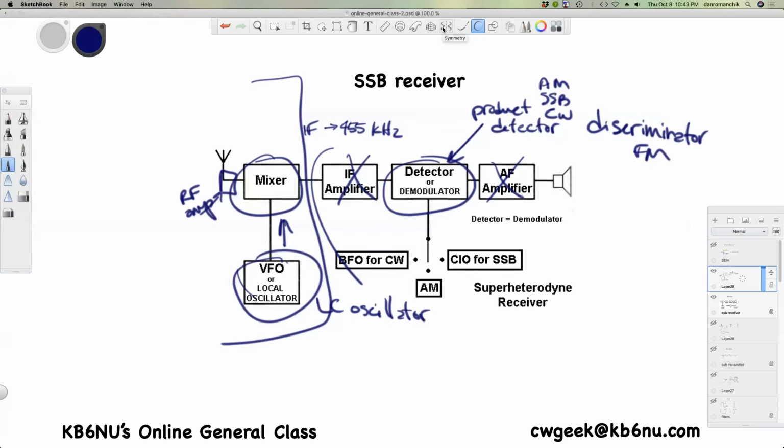That's why you sometimes had to warm up your radio before you would use it, because you wanted the most frequency stability. After the temperature in the radio stabilized, then your L's and C's and the oscillators would stabilize.